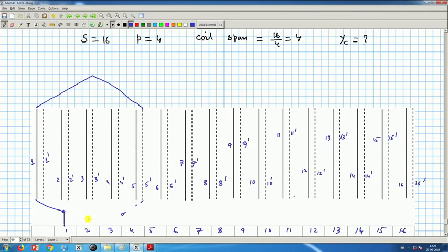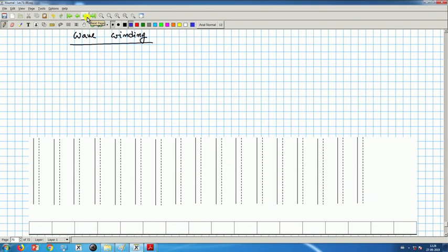Now, the ends of a particular coil I will terminate in a different way in case of wave winding. What they say is, you terminate this end two pole pitches apart in terms of commutator segment number. Got the point? So I will do that. Here, I want this once again, another is there, 16, same thing.